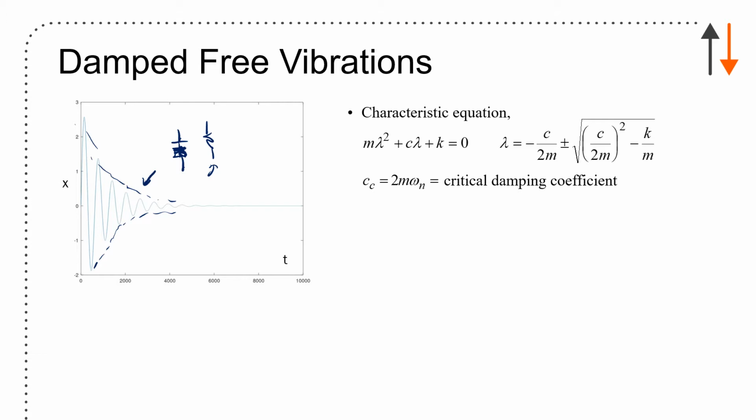And then we say your critical damping coefficient is twice mass times omega n. But remember, it's based on this equation where you have to calculate c equivalent, k equivalent, mass equivalent. And often you normalize by everything, so you know what all the terms are.